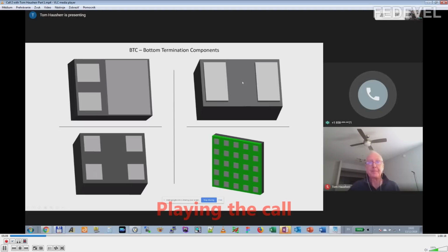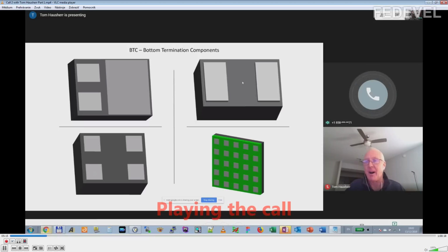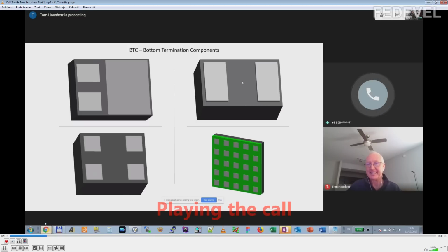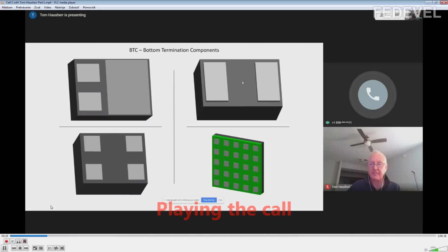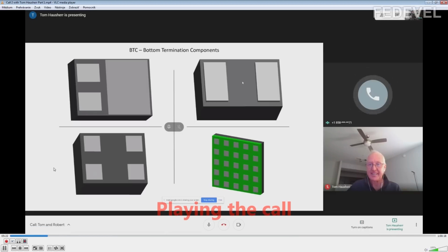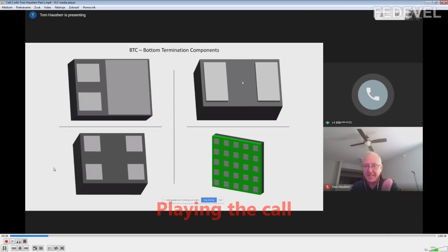Okay, but it's really only 1 millimeter by a half millimeter. It is so small. It's micro small, right? You could put 1,000 of them in the palm of your hand, okay? And therefore, the pad size and shape have to be very, very close to 1-to-1 scale of that component lead, okay? And the same thing with the land grid array.